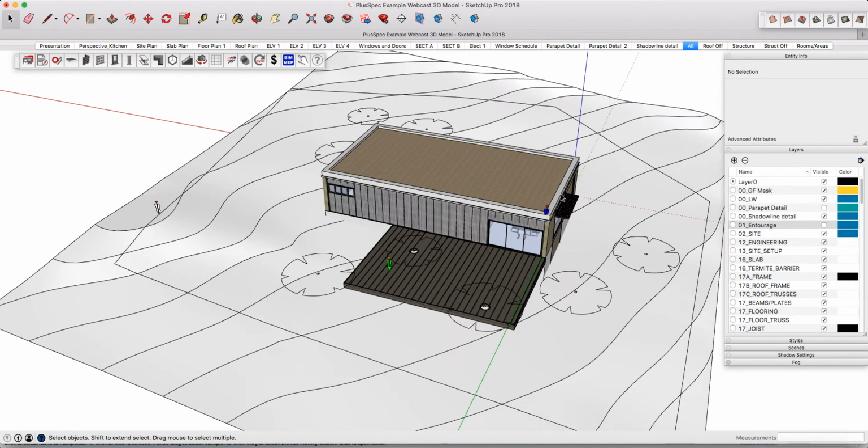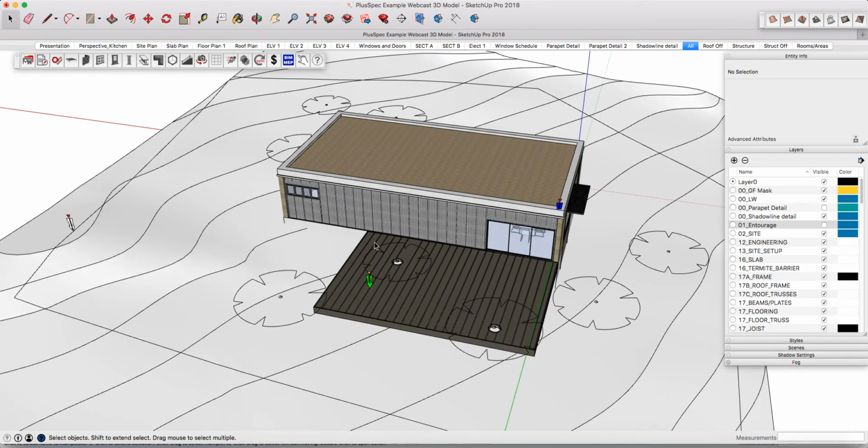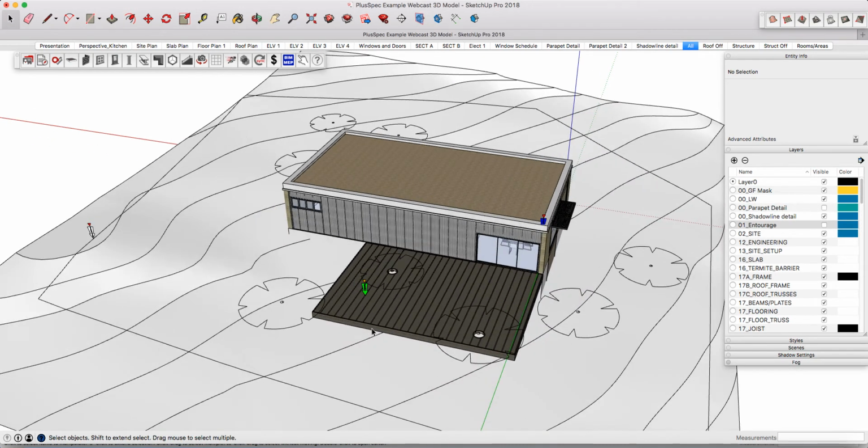But over time, you might have like 50 plus tags, especially if you're doing it from start to finish, or if you're a builder contractor creating your estimate, you might have a hell of a lot of provisional allowances and you might be putting in a bunch of other tags to communicate back to the architect or designer or whoever it may be. And you can access each individual tag. So you can right click on a tag and then show tag info, and that's going to bring up the dialog.